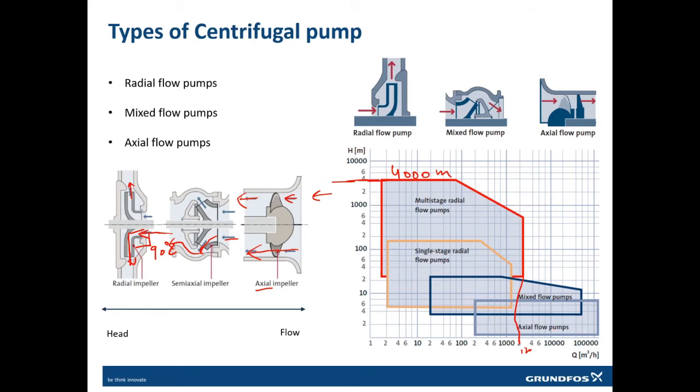Then in between you will find mixed flow pumps. I will talk about single stage and multi-stage in a while. You will find single stage for certain pressures, and if you need even higher pressure, you have to go for multi-stage radial pumps. So pumps can deliver very high flow and very high pressures. It usually depends on the application which pump will be used where.